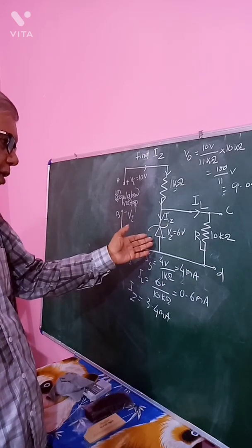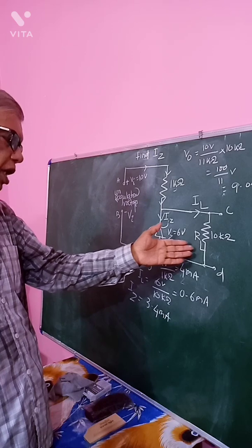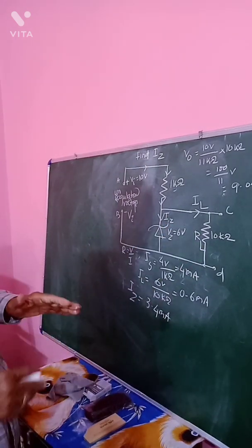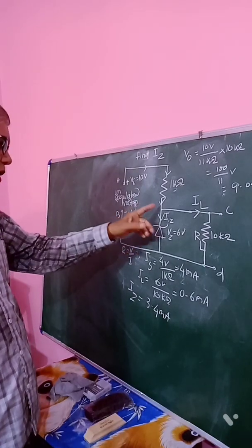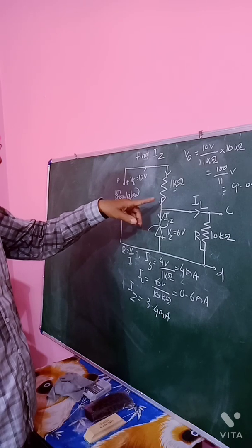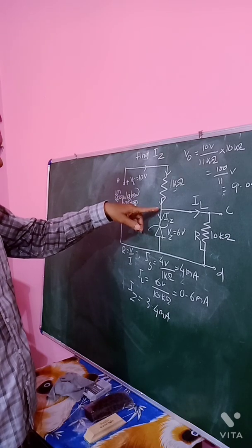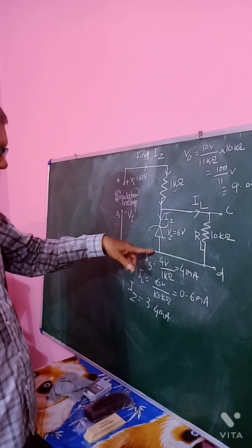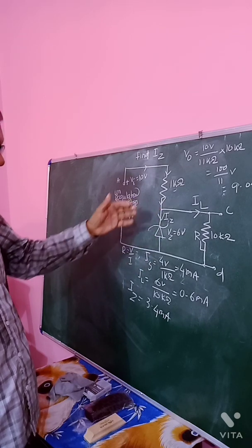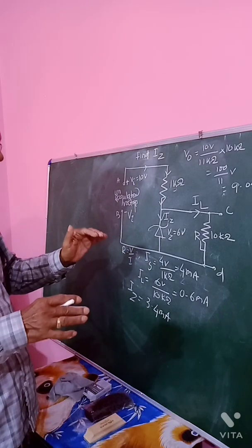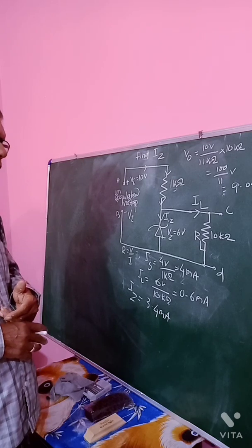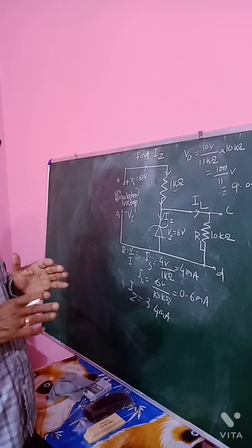Now we are regulating that potential to a value equal to 6 volt. So a very important point is that if you allow the current to increase, then the incremental current passes through the Zener diode, because at this point of Zener breakdown the resistance becomes very small, allowing current to pass through, maintaining a constant potential.